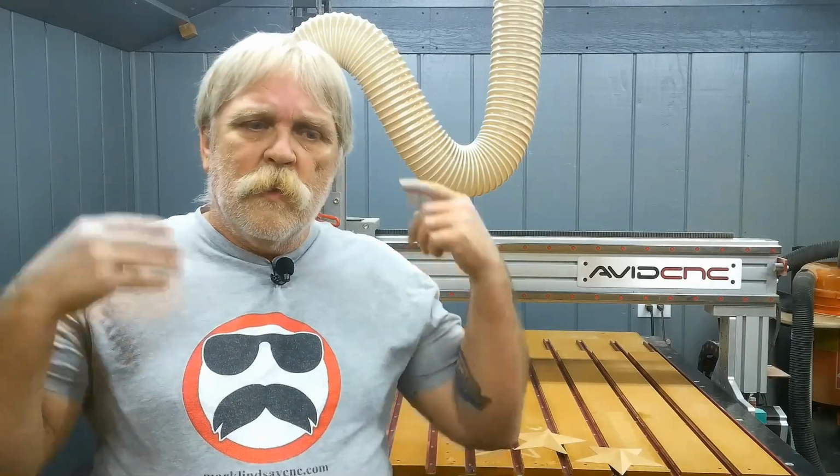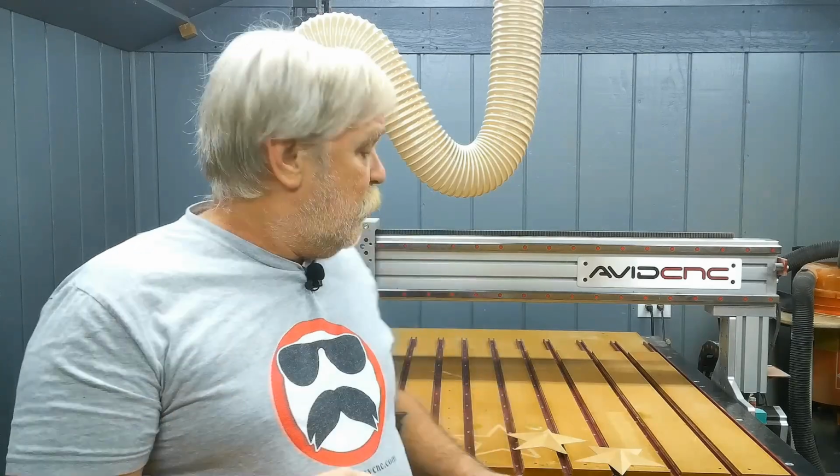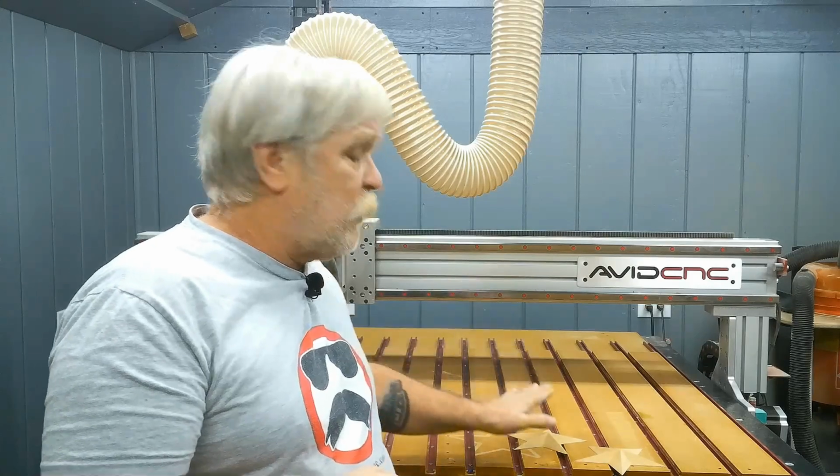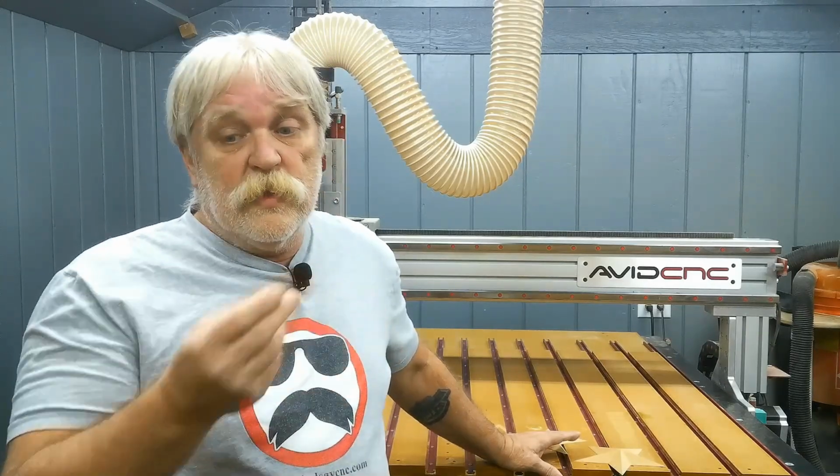And there are lots of other situations where one is better than the other. So use your judgment. Preview early, preview often is what I like to say. And if you need something to a certain depth from the machine bed, use the machine bed. If you needed a certain depth from the material surface, use the material surface. And as we've demonstrated, it can be both, whether it's the same file or 2 different files if you're using an older version of the software.